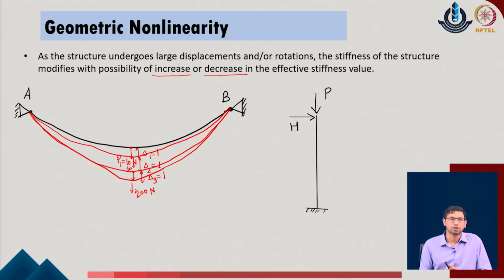So, what typically is happening in a given system is that as I increase the displacement with the same magnitude, with the subsequent increments in the displacement, I require a larger amount of force. That means there is some stiffening taking place in the given system, or ideally I can say that the stiffness of the system is increasing as I pull the system more downward, and this is offering more resistance to give the same amount of displacement.